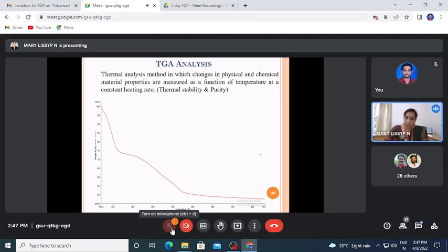Now you can see the example, the graphical representation here for the TG analysis. It started at 41 degrees temperature and went till 861 degrees. In the beginning, you can see a rapid weight loss. It is mainly due to the loss of moisture. But then a gradual degradation has taken place when the temperature went from 100 to 450. Then from 450, you can see it is almost stable. So these are the changes that happen to the material.